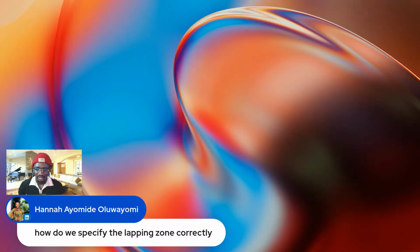Sorry, can you help me clarify what you mean by the lapping zone? Are you talking about at what point you lap the bars? If that's it, okay, definitely. If you have bars in two different panels and you want to lap them over your support, automatically, once you specify the lap length, it creates that lap over the support.